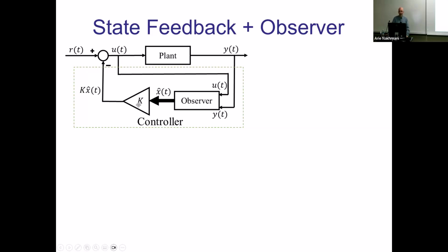But here's the problem. Why does that thing even need to converge in the first place? Because now you are affecting the actual plant with your new signals, right? So you modify U completely based on the estimated X, and the estimated X at the beginning is not even the real X, it's just starting from zero initial conditions and maybe starts to converge to the real X. It's a completely different set of numbers, not even close to your original x0 state when you start the system.